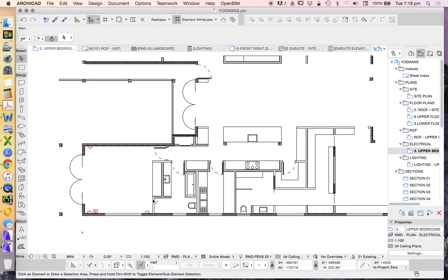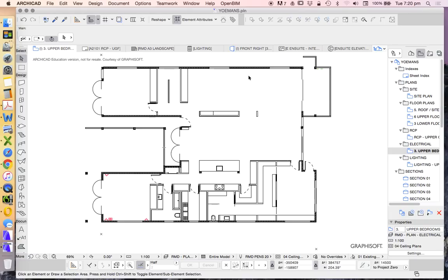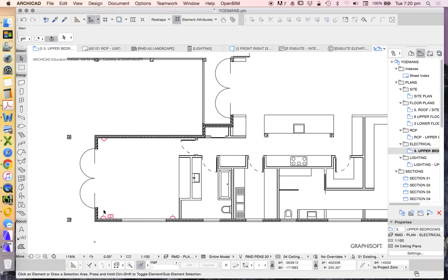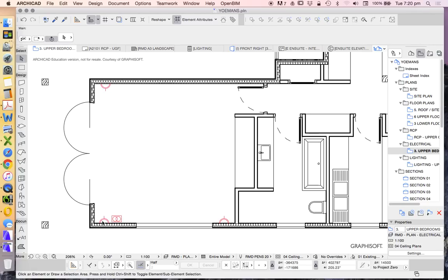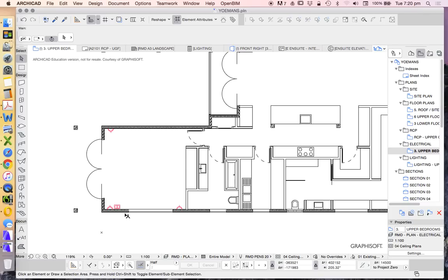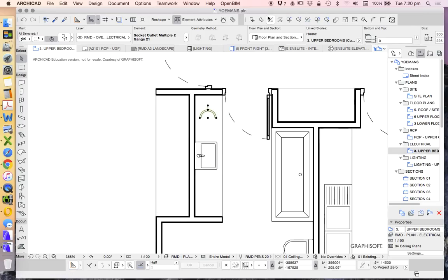When I do my electrical plan, I base it on a floor plan. I just simplify it. So you can see that I've taken out some of the information based on the flooring, some of the information based on furniture, and I'm showing some symbols. The way that I'm doing that in this case is that my electrical symbols are red, I've just started here, and the intention is that once I've created one, I can then just duplicate this and place it where I want it to go.